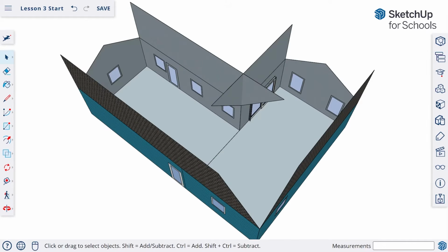Because the building has 2 sections, the main living space and then the bedrooms off to the left here, we need to separate them into 2 areas of the model and then unfold those groups down and around that ground plane. This allows us to keep the ground as a surface that we're going to fold from. You could alternatively not print out the floor, and that could make it easier to physically put back together, but that's really going to depend on how complicated your model is.